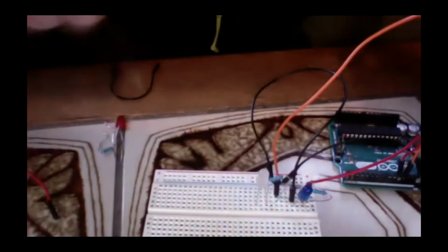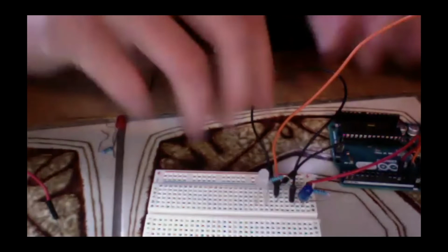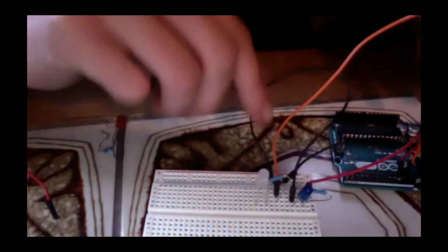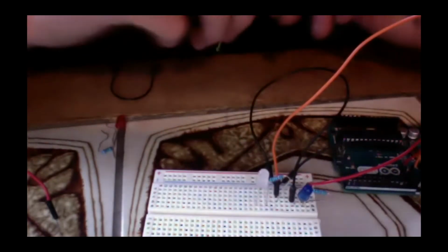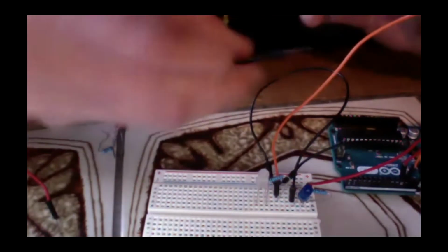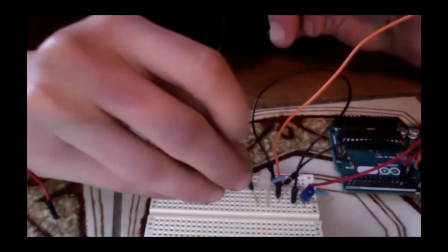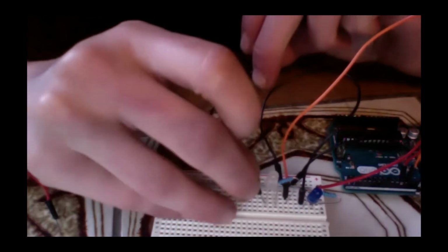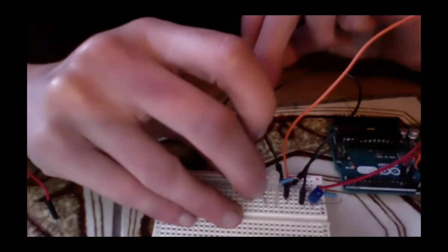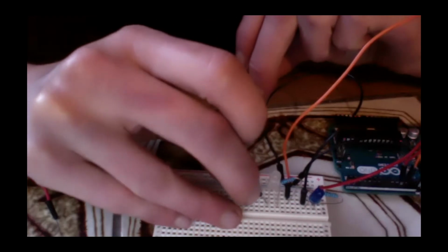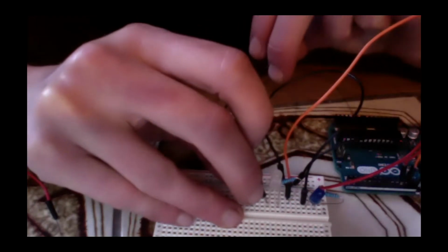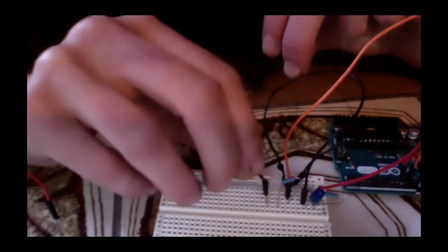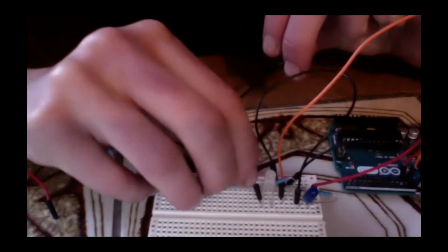And then we finally get our ground wire. And because we already have the ground connected up onto the breadboard here, all we need to do is take one end of the black wires and put it to the shorter end of the LED. So that would be C11, because our short leg is in D11. So we're going to go below that into C11 for our negative, for our ground.